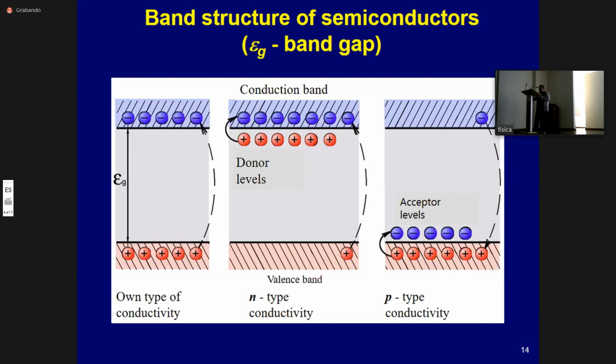This region of the semiconductor, where the type of conductivity changes, for example from electron to hole, or conversely from hole to electron, is called the transition region. In the transition region, the concentration of the equilibrium charge carriers is several orders of magnitude lower than in the rest of the bulk of the semiconductor. The transition region is the main working region of a semiconductor detector.